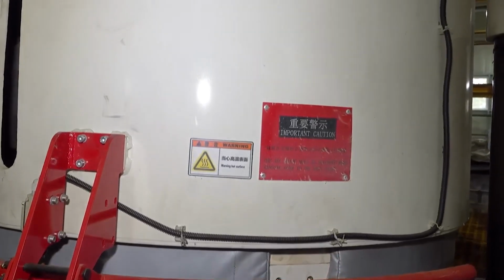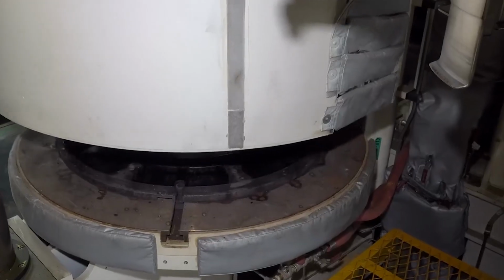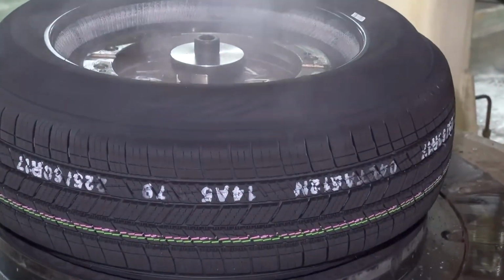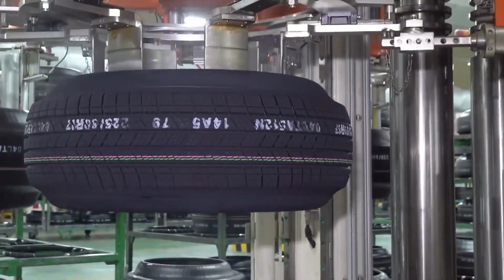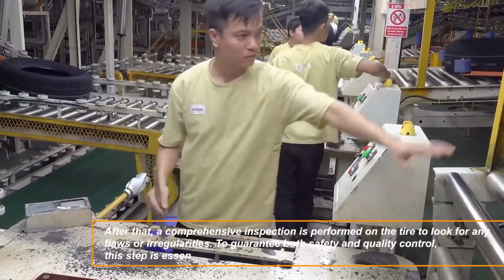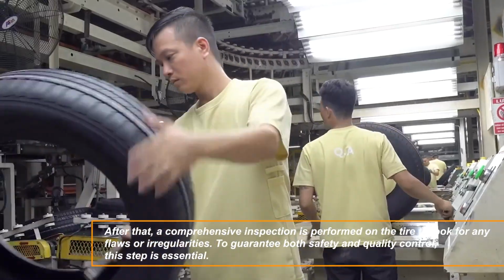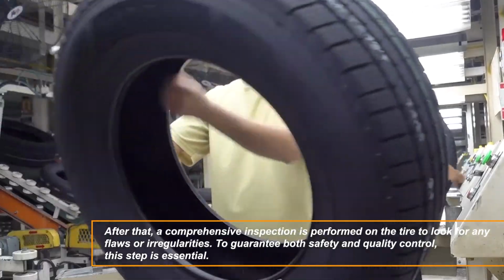In addition to molding, the rubber undergoes a chemical reaction known as vulcanization over the duration of its stay in the hot pressurized mold, which changes it from a weak, sticky material to a strong, elastic one. Excess rubber is cut off after it has cured, leaving a neat and tidy tread surface. After that, a comprehensive inspection is performed on the tire to look for any flaws or irregularities. This step is essential to guarantee both safety and quality control.